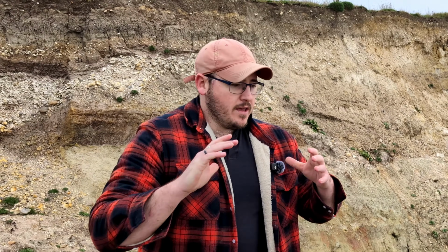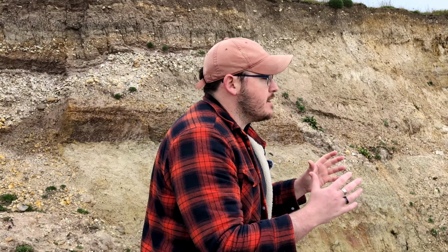So I've got an observer with me, my beautiful partner Ada, who's behind the camera at the moment. She's going to be acting as the responsible observer here while I'm the pilot in command. We've set out a safe takeoff and landing space. We've got a little bit of emergency procedure in place, and those are important. Have all of those things ticked off and in mind when you are flying a mission like this, just in case things go wrong. And that's all it takes half the time. Just be mindful. So let's capture some data.